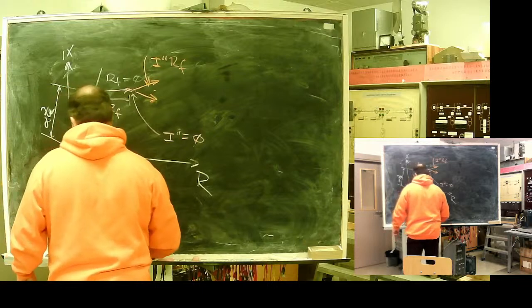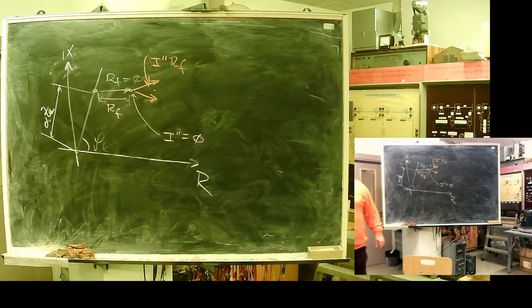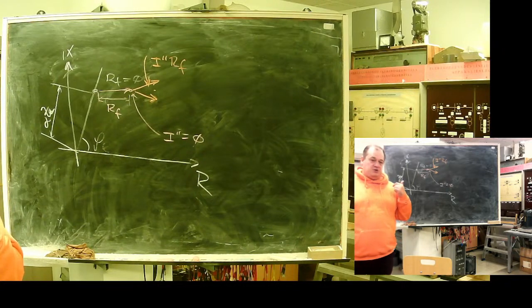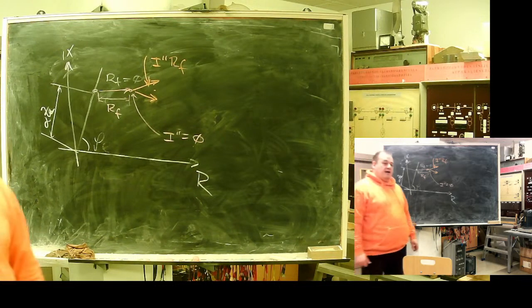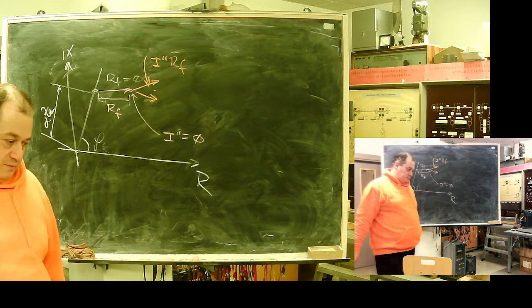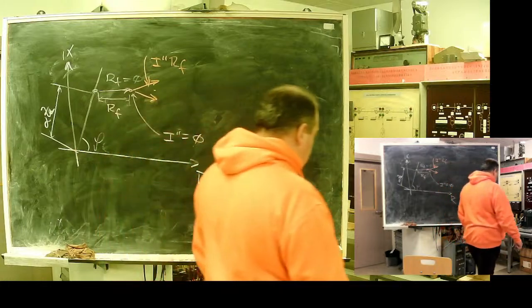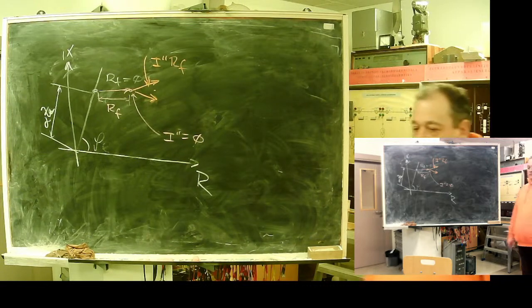This resistance may have a virtual part, it's not real, it's imaginary part visible to the relay. In reality, transient resistance itself is active. It's very, very low inductance. But the angle shift between currents from system 1 and system 2 causes the appearance of this virtual imaginary part, virtual reactance.